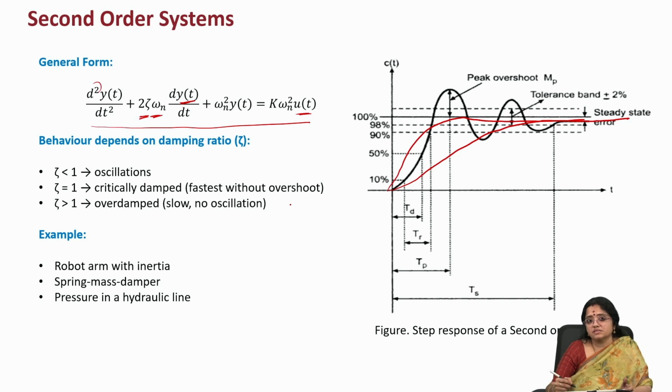Depending on this natural behavior of the system, we have to decide what kind of controller and what controller parameters are suitable to regulate the system smoothly, with the required precision, accuracy and robustness, depending on the objectives of the control. To make such a decision, we need to know the model of the system. If there are two accumulating devices, we go for a second order system. Accumulation here means mass accumulation or energy accumulation within the system. If there are three accumulating devices connected in sequence, it will be a third order system, and so on.